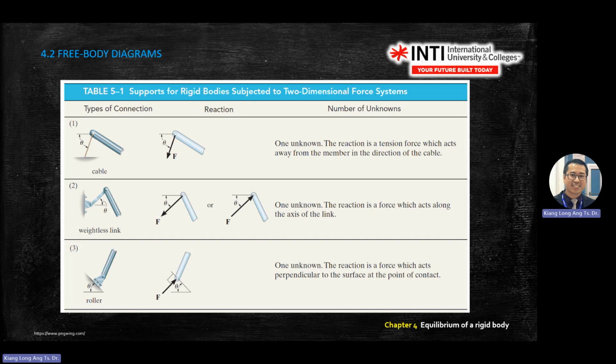No matter what, let's say I give you a slanted surface. There's a roller up there. The contact point is here. The normal force is 90 degrees to the surface. So don't draw the diagram like this. If you draw it like that, it is wrong. There's no normal force like that. The normal contact force is 90 degrees for all round bodies. Take note of this one.